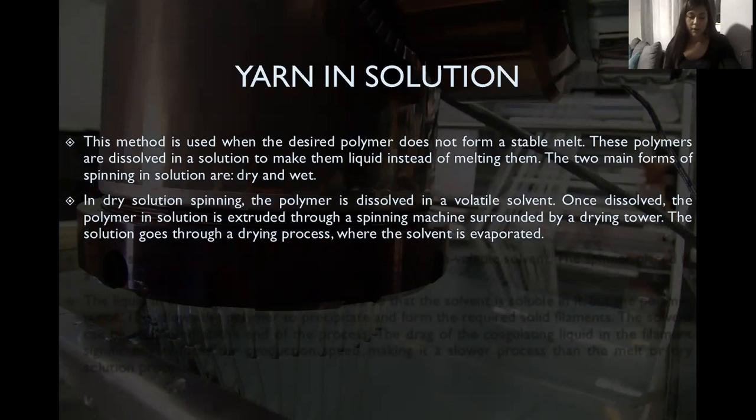Once dissolved, the polymer in solution is extruded through a spinneret surrounded by a drying tower. The solution goes through a dry process where the solvent is evaporated.